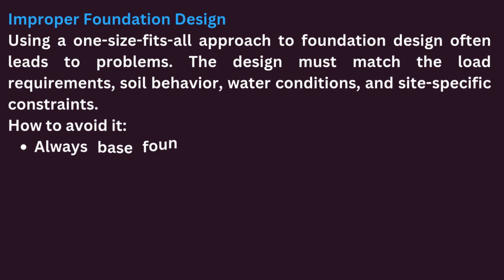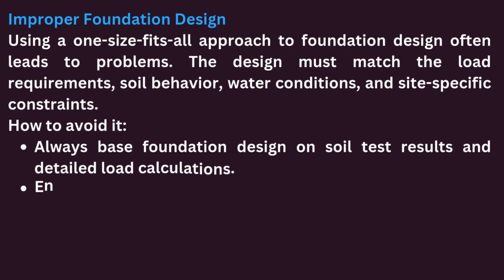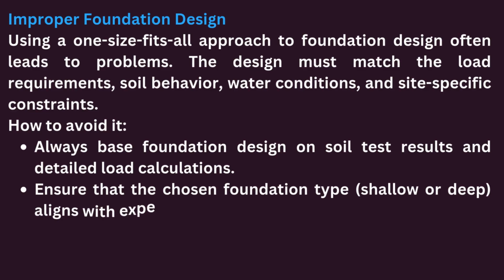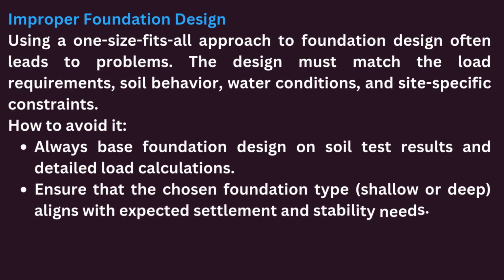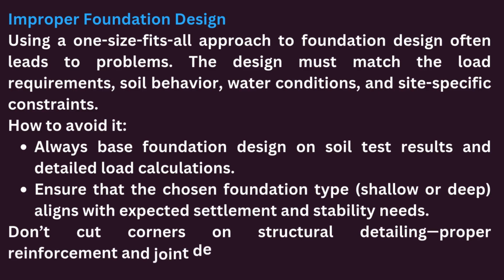How to avoid it. Always base foundation design on soil test results and detailed load calculations. Ensure that the chosen foundation type, shallow or deep, aligns with expected settlement and stability needs. Don't cut corners on structural detailing. Proper reinforcement and joint design are essential.